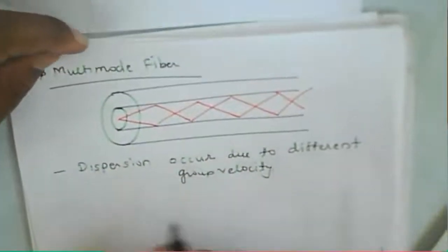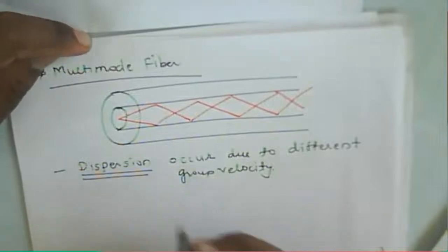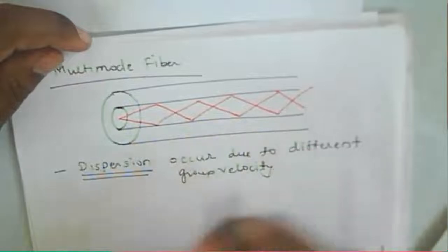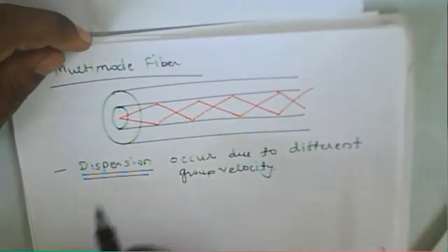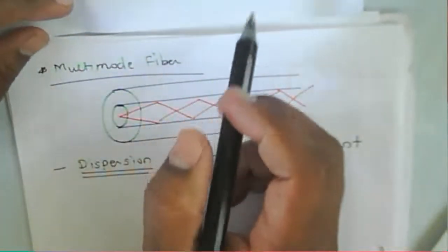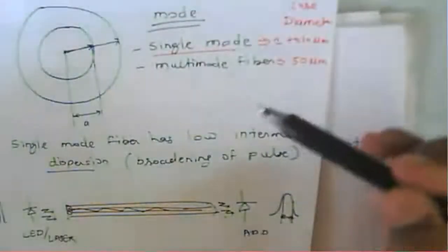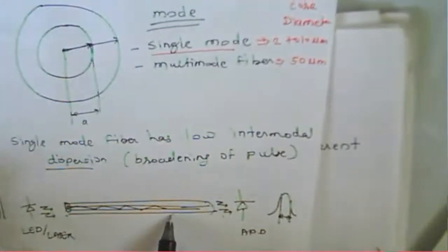Okay, different group velocity there. Now because of the different velocity, pulse broadening occurs there. But if we consider that the fiber is to be used in terms of bandwidth for a single mode fiber, we can say that is what decides the data rate and particular bandwidth. If you consider that, the bandwidth used here is large.